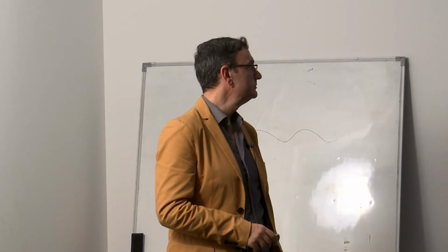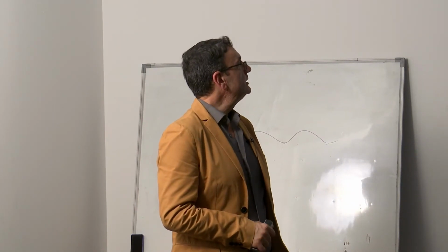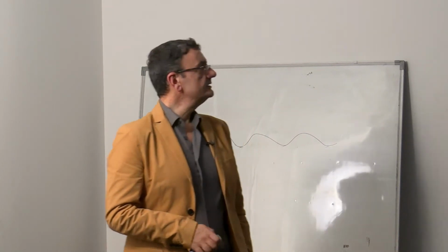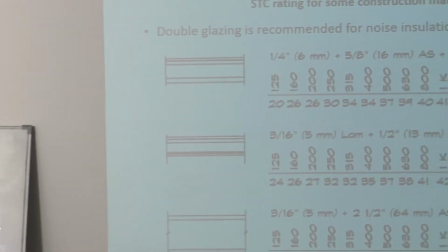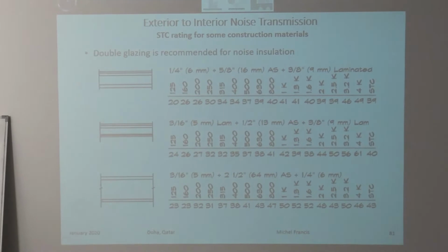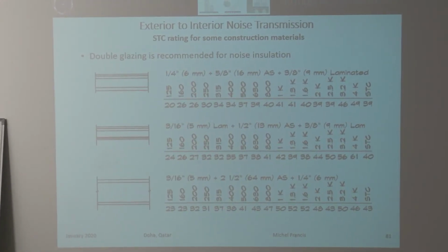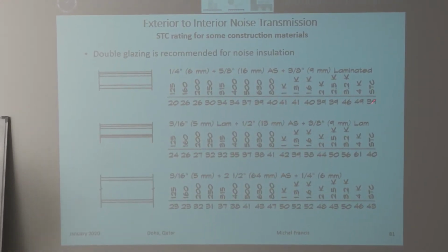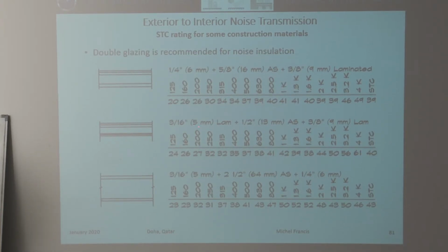Sell on the catalog. These are again different materials. So you have laminated glass. Do you know what laminated glass is? Laminated glass means pieces of glass laminated together, stuck together. A sandwich panel without an air gap in the middle. So you have here 39. This one is 5 mm laminated, then an air gap, and then 9 mm laminated. That's going to give you 40.